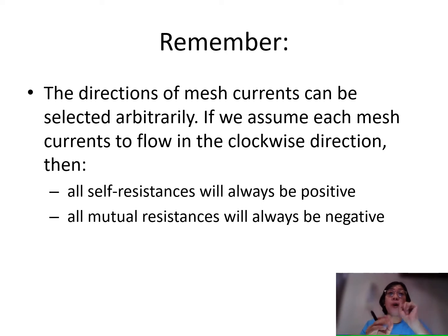However, all mutual resistances, those resistances being shared by two different mesh currents, will always be treated as negative. So self-resistances are positive, and mutual resistances will always be negative.